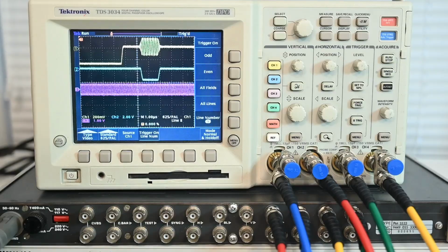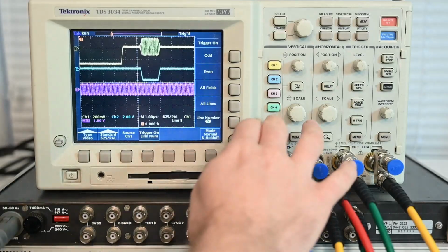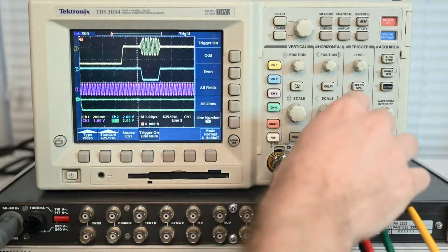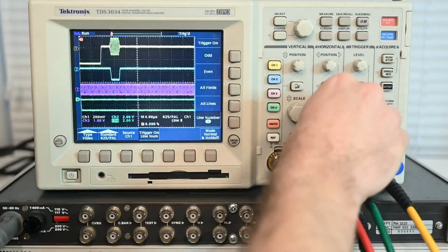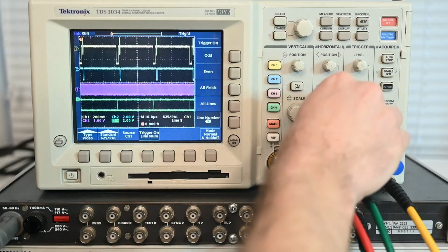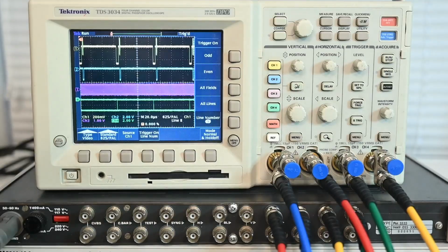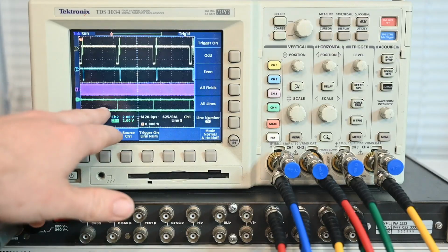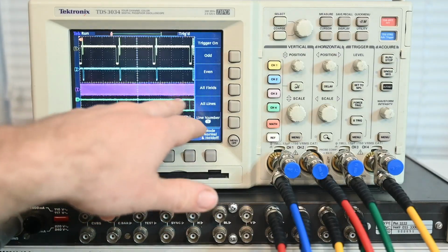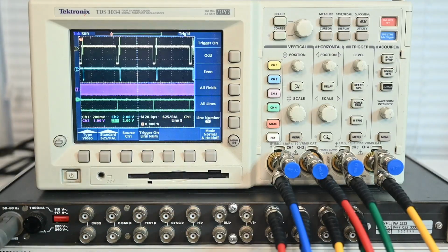So, just looking at this, we can see for a piece of video equipment which has all of these individual sync signals available, just how ridiculously easy it is to compose a video signal. And if we switch on channel number 4, we have that special PAL-specific signal. This is the PAL ID, or some people call it PAL index, which is basically indicating whether or not the phase is inverted or alternated for this particular line. As we can see, it's a square wave that changes polarity on each line, as you would expect.